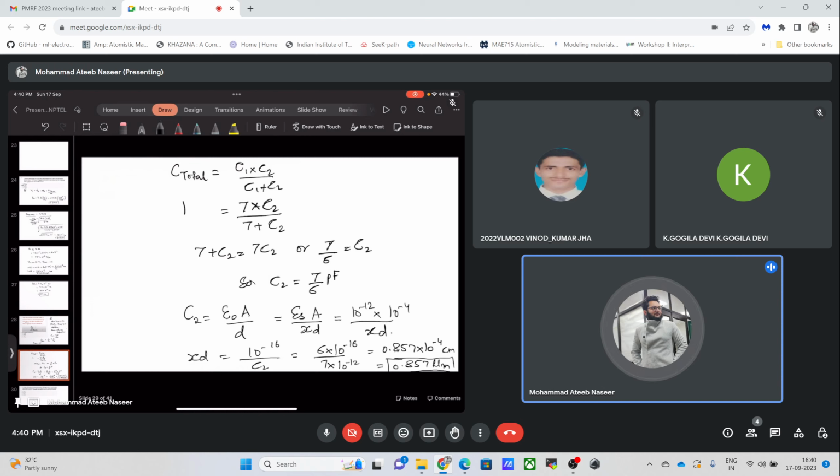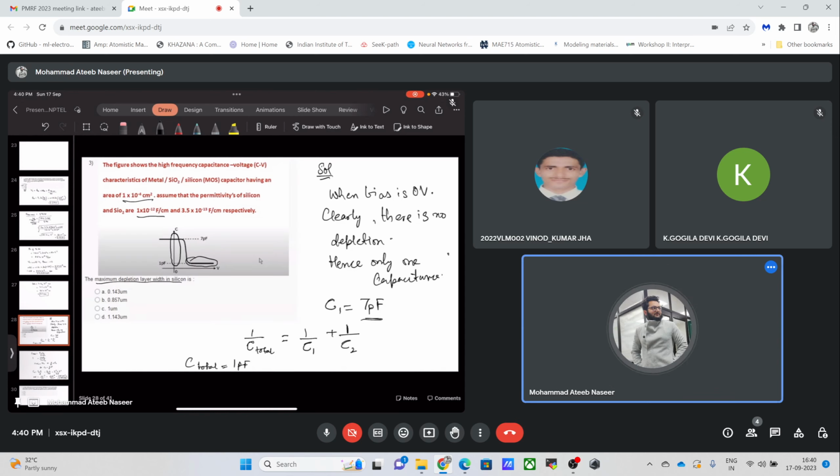We have observed how this MOSFET behaves under the different biasing conditions, with the depletion region being identified by this hump, this transition over here, and then the inversion region.